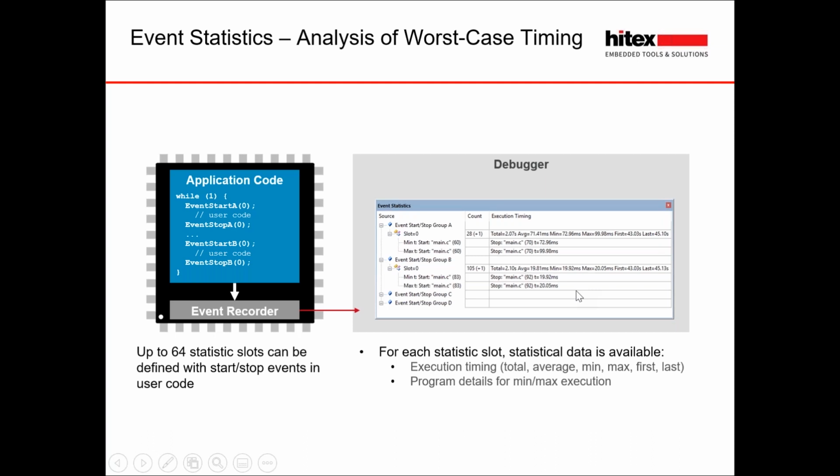Again, if we're developing a component for reuse, this means that we can also start to characterize it as well. From the compiler, we'll get its code and RAM usage. But here we can also start looking at its runtime performance as well. So when we're starting on a new project, we know what components we're going to use, we know what resources they're going to use, and that will guide us in selecting a device. Again, the more we start to think about the architecture and code reuse, the more benefit we get from that system.